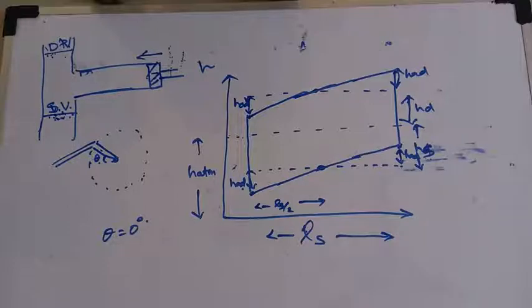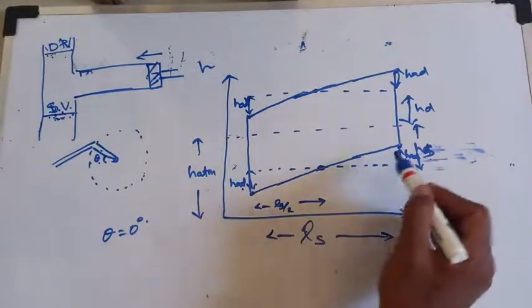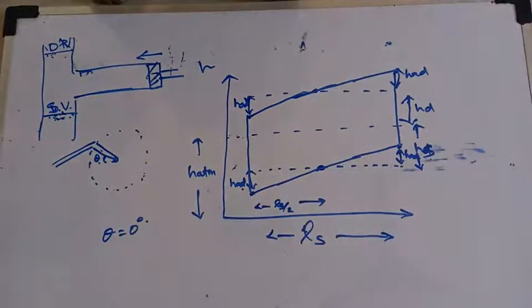By this we saw that because of this acceleration, the indicator diagram changes, and it also causes an advantage. During suction, it increases the suction pressure and decreases the delivery valve pressure. During delivery, it increases the delivery valve pressure and reduces the suction valve pressure. So we can conclude that here also the area of this indicator diagram will be equal to work done only.